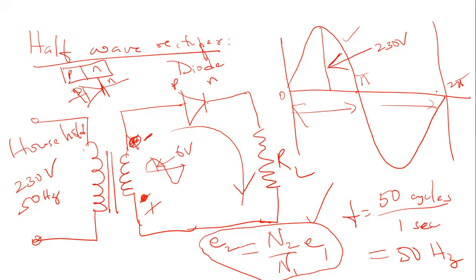So if the PN junction is reverse biased, like we explained in the IV characteristic curve, no current can pass through the PN junction. The current passing through the PN junction is only in microamperes. Those very small currents are due to the reverse saturation current, like we explained yesterday. Then we can say that no current is passing through this PN junction under reverse bias.